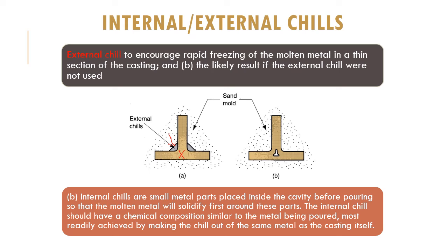So this will help to freeze this area faster, so that there will be no shrinkage cavity inside the part.